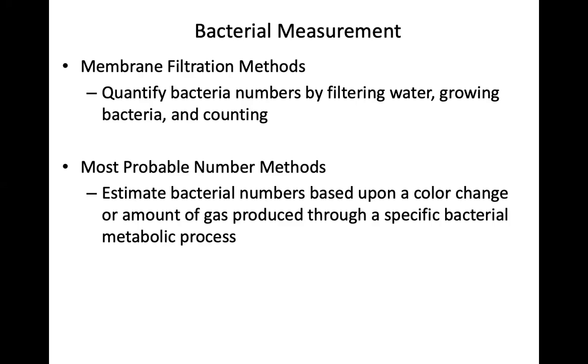Now, if you have water and you want to determine the number or the presence of microorganisms, you can use what we call the membrane filtration method, where you would have a given volume of water in a glass container, then you find the 0.45 micrometer filter paper.